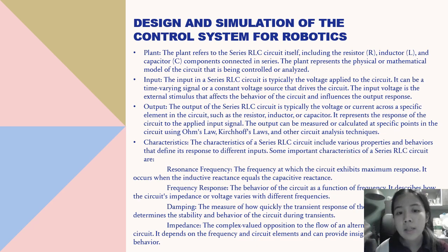And the characteristics of the RLC series circuit are the various properties and behaviors that describe how the circuit responds to different inputs. Some important characteristics: the resonant frequency is the frequency at which the circuit exhibits the maximum response, occurring when the inductive reactance equals the capacitive reactance.